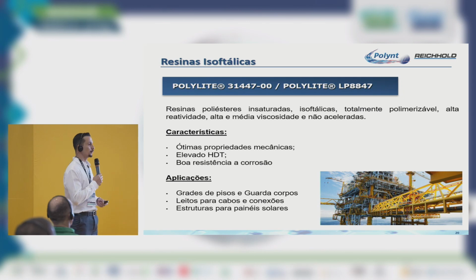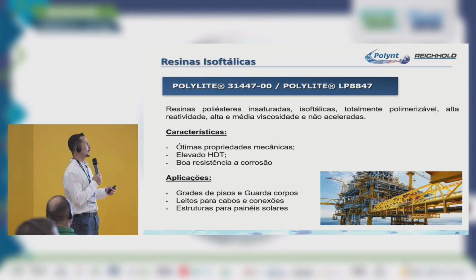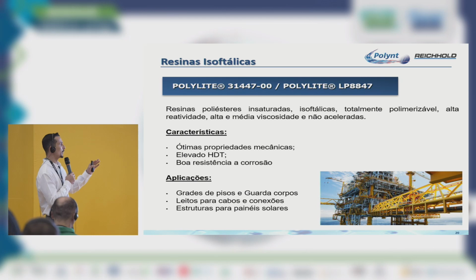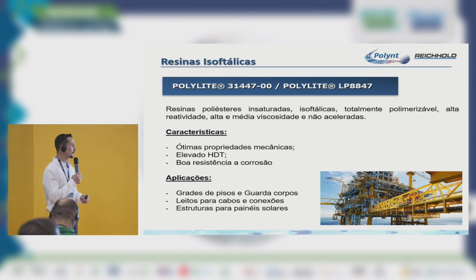For isophthalic resins in our portfolio, we have Polylight 31447 and Polylight LP8847. These are unsaturated polyester, isophthalic, polymerizable resins which are highly reactive. They have high and medium viscosity, and neither of them is accelerated. Features: they both have excellent mechanical properties, 110 degrees of HDT and good corrosion resistance.